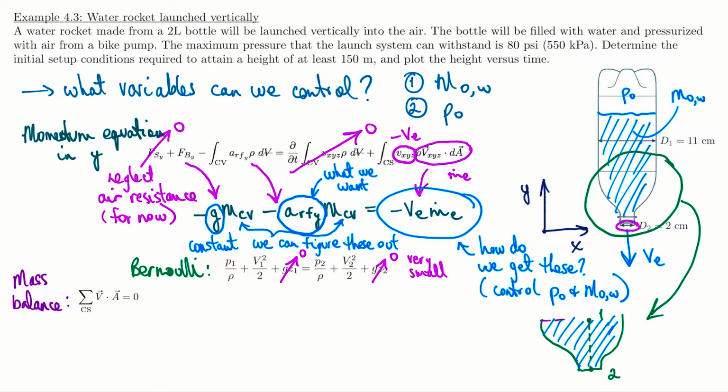So in our case, at point 1 of our control volume here, the velocity is entering and the area would have a normal pointing outwards, so that would be negative. So it's the sum of all the control surfaces: negative V1 A1. At point 2, the flow is exiting, the same direction as the area, so that's plus for the dot product, V2 A2 equals 0. I can simplify this in terms of V1, just rearrange it.